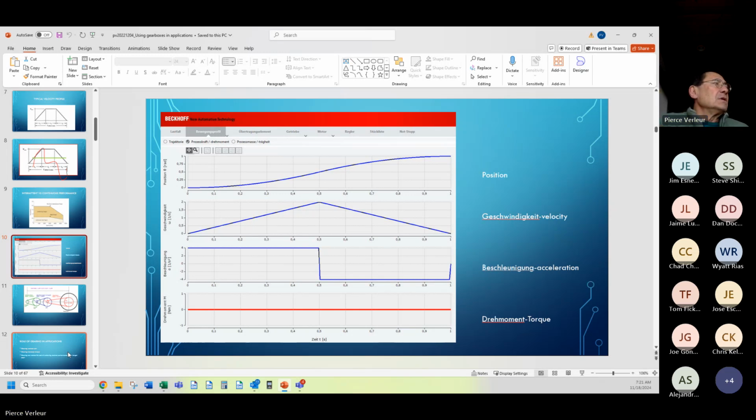And it often comes from the software associated with the servo amplifier. And in some cases, you can do some predictive charting if that servo amplifier has that capability in its associated software. So make use of this as you go ahead and try to size things.